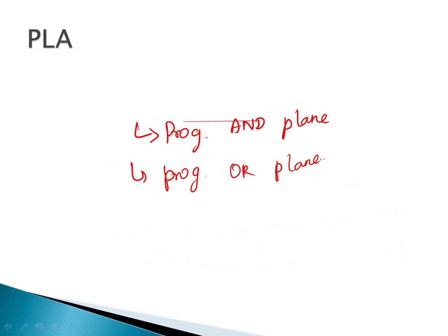Because both planes are programmable, PLA is highly flexible. It can also share the product terms among multiple outputs, which makes it very efficient when multiple Boolean functions have common logic. Therefore, the PLA is ideal when hardware optimization is required.